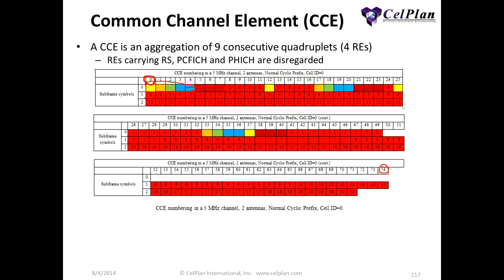You can see that it's not contiguous. Then you have CCE 1. Remember that this is one after the other. Then I have CCE 1 until here, CCE 2, and so on. So in this case, I have 17 CCEs that are a large one, and the last one didn't fit because it has only 8. So I have 18 CCEs in reality, starting from 0.